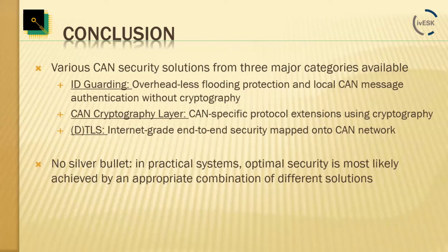Just as a quick outlook, what we do in the CAN cryptographic layer is that the system can lock itself. We assume that if we are powering up and do not have a key, we are still in a safe manufacturer or system integrator environment, and the devices simply generate their own specific key in that cycle the first time the system is powered up, so that it locks itself on power up. This could be one option on how to simplify key generation.